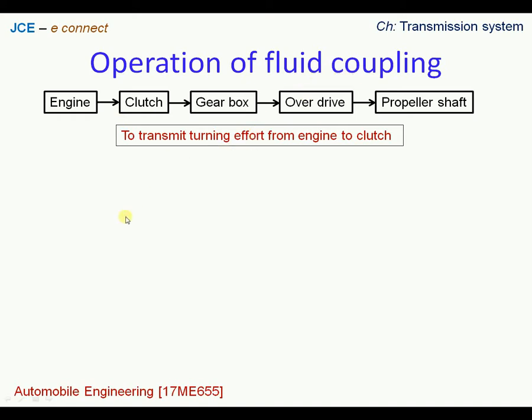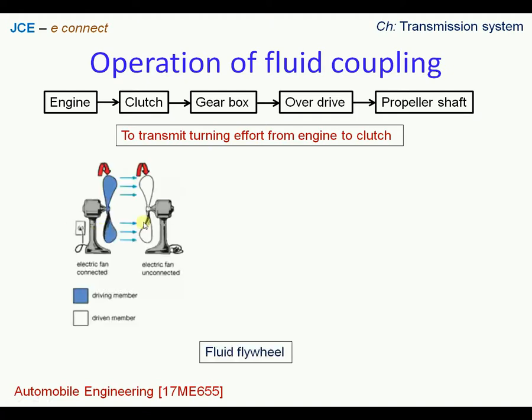Now let us look at the principle of operation of fluid coupling. Let us take two fans here. One is connected to electrical power, the other one is switched off. When one fan is powered, the fluid stream strikes the blades of the other fan, and the other fan's blades are set in rotation.